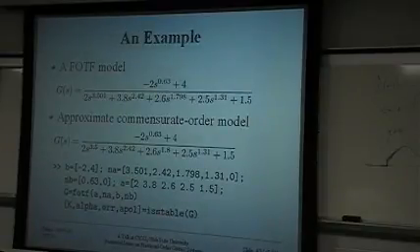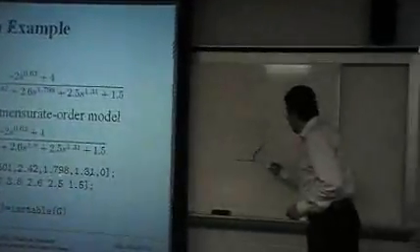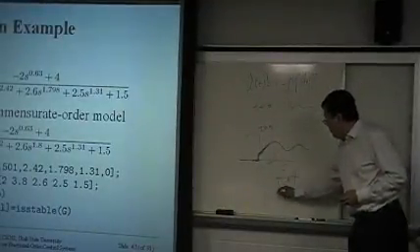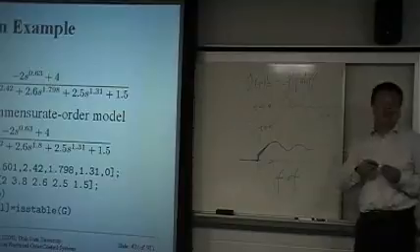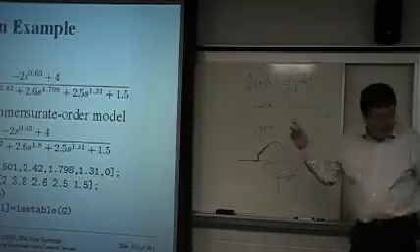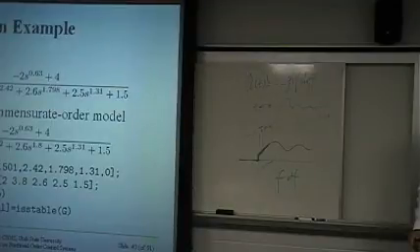In fact, I have defined the function FOTF in the directory TF. And if you have an integer order system and call the FOTF function, it will be converted into a fractional order transfer function automatically. So you mean to say if I gave an approximation of a fractional order transfer function and call this, it will give me that? Yeah. Oh, that's good.